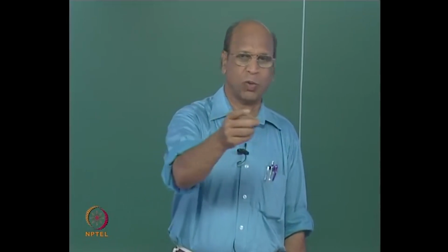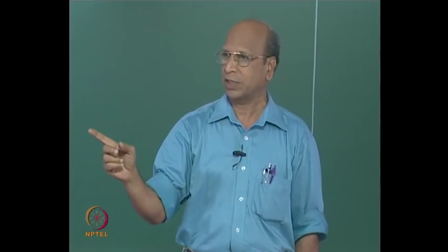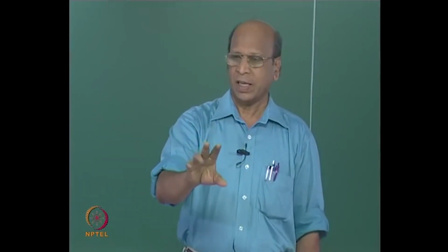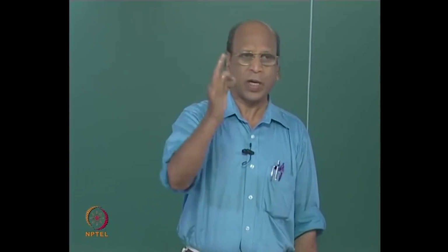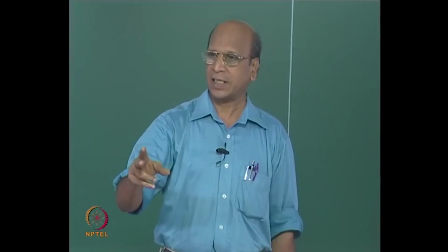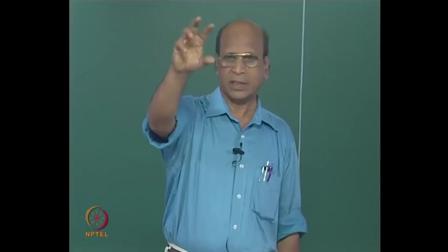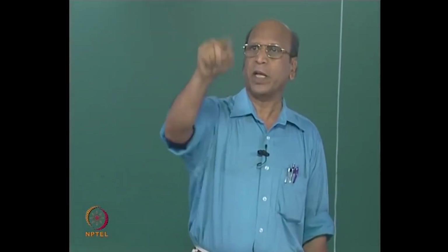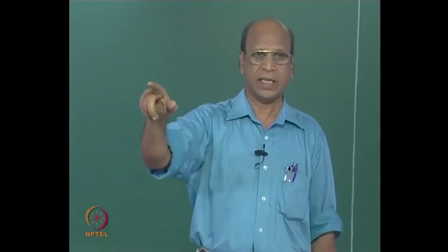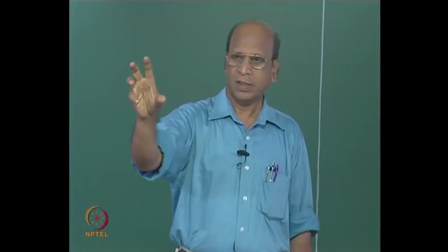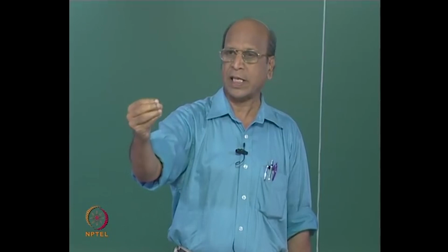And if you go to Hougen-Watson models, I asked what is the information you get from the Hougen-Watson model, that is one of the questions, and not even one wrote the correct answer. Maybe one or two people. You get only one rate expression, that is all, nothing else. A rate expression for catalytic reactions is a very peculiar rate, because you have something in the denominator as well as in the numerator. Take simply A going to R, a reversible first order reaction, taking place on the surface of a catalyst. So it is a catalytic reaction.